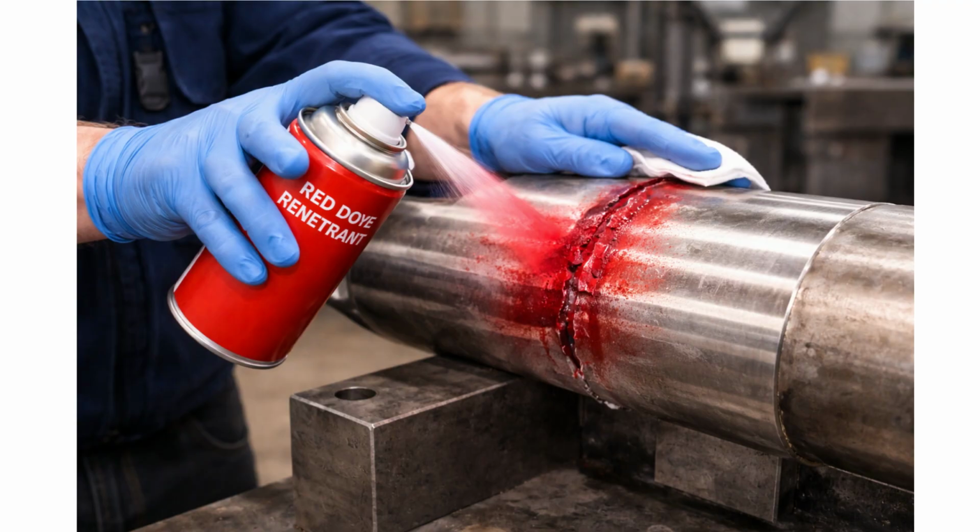Most inspection kits use aerosol spray cans because they're incredibly versatile. You can take them up ladders, inside confined spaces, and into difficult-to-reach areas. The penetrant itself is specially formulated to have very low surface tension, which allows it to flow easily into even the tiniest openings. It's this property that makes the whole method work.